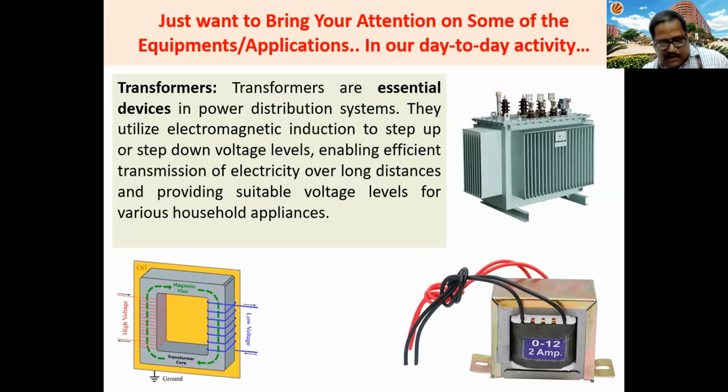So this is what we say mutual induction. So we are getting energy because of some flux created by some other circuit. But this flux also links with its own coil, the red coil also. The flux you can see here is marked with this green line on the transformer core.